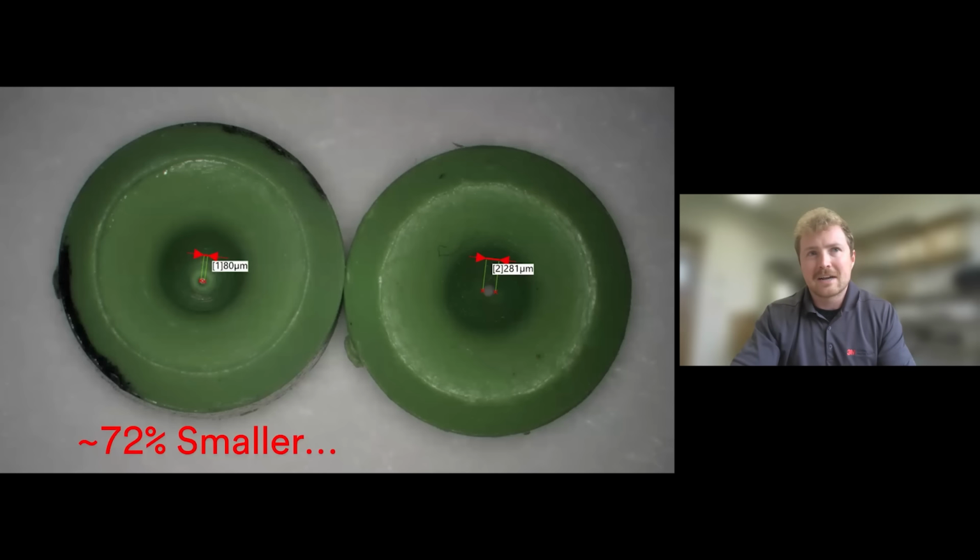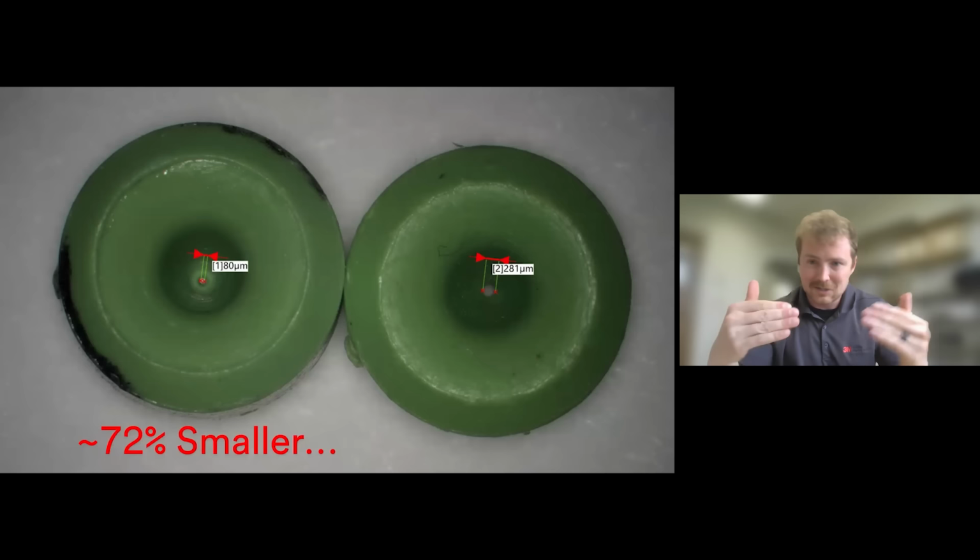And I quickly was able to determine that the orifice size, so what determines your dilution rate, was different than the new one versus the one that's been in use. It's actually quite a bit smaller. And based on doing the measurements, it was roughly 72% smaller than what it should be.